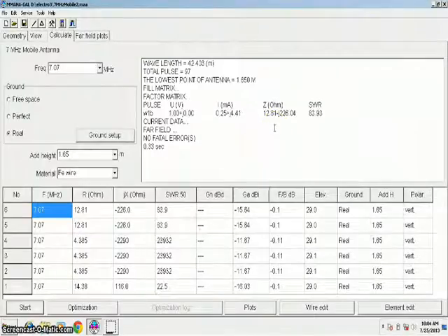And reactance here down to minus J 226.04, but still not zero. This needs to be plus minus J0, and still minus, means the loading coil value should be added.